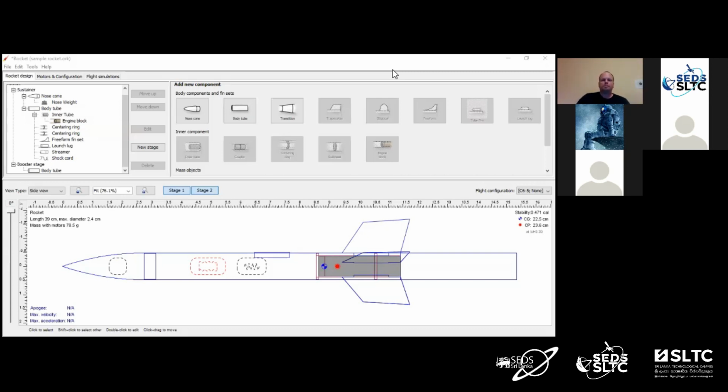Okay, so again, in this case with the little black powder motors, it's just the thrust coming out. This motor is going to start burning, and hot exhaust gases are going to be coming out at a very high speed. That's what's propelling the rocket upward. That's the thrust. It's also what's going to separate the stage, because the upper motor is just held in here loosely with a little bit of friction. I can shake it and it doesn't fall off, but if I give it a little bit of pull, it just falls right off. So it's the thrust from the upper motor that's pushing this away.